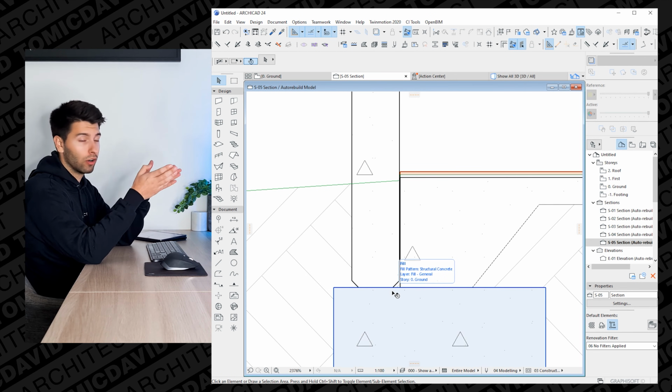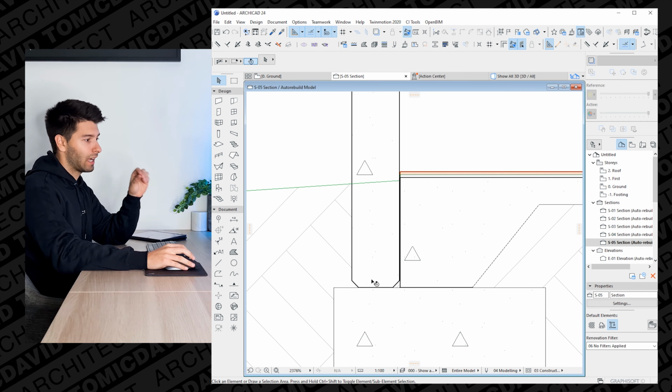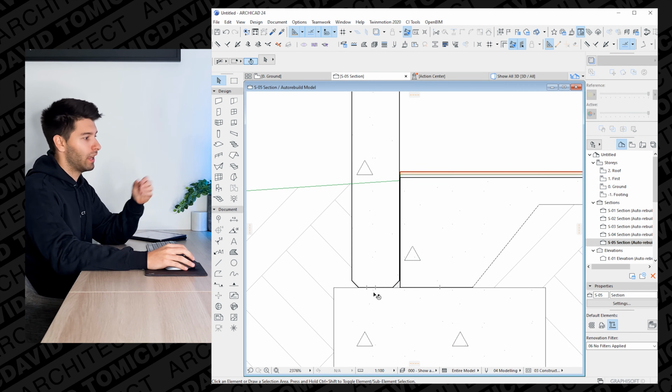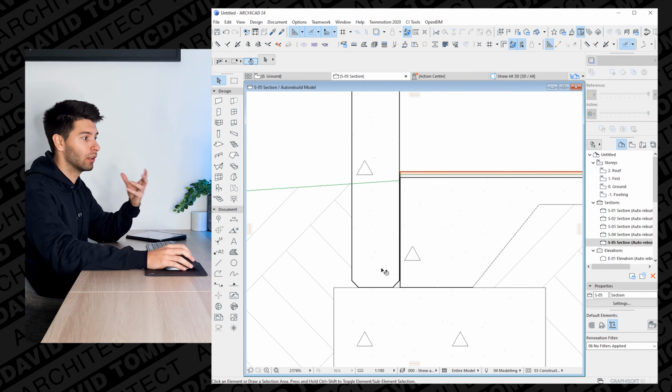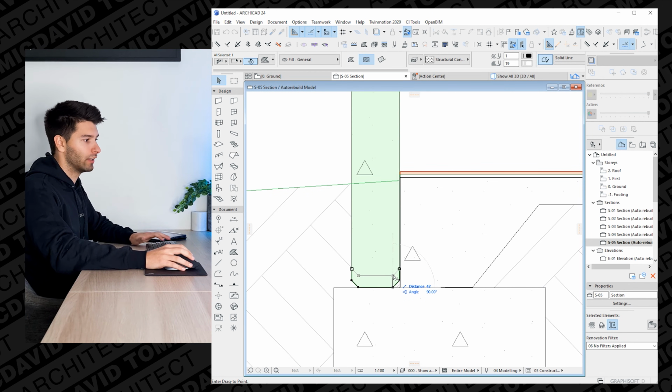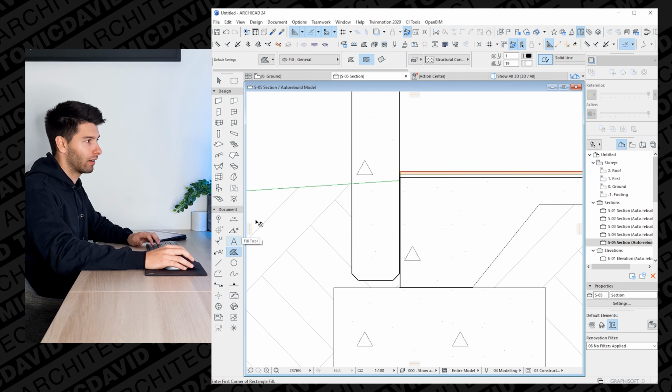So that's just how a concrete panel is made. It does have the small chamfers on the edges, so you can actually draw them in. You don't have to if you don't want to, but it is a nice detail and it makes this detail a lot more clean, a lot more thought out. I'll then move this up about 25 millimeters so we can insert our packer underneath.